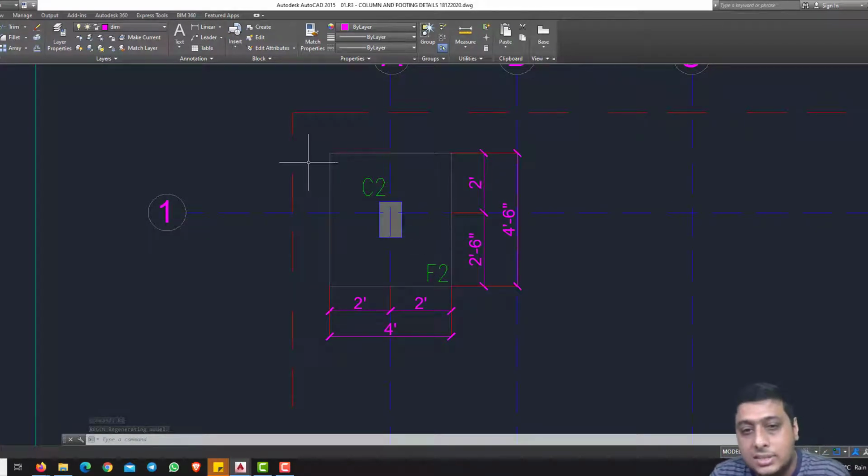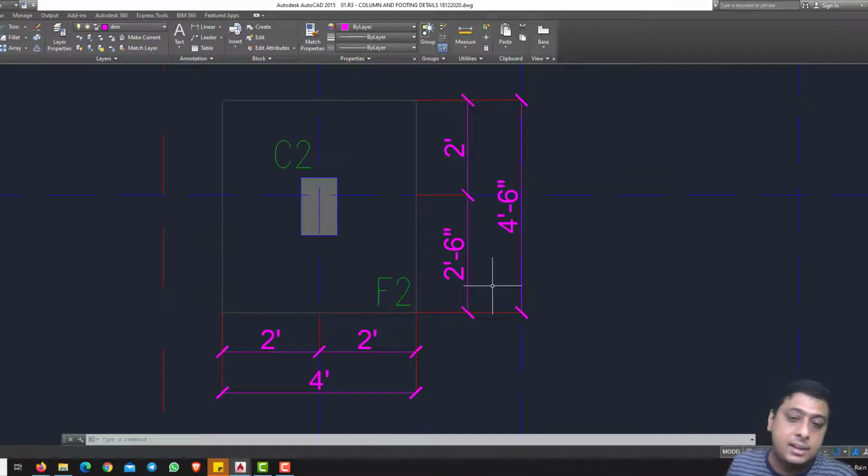So with respect to the foundation, the length and width of the foundations are very, very important. Generally, the length and the width of the foundations are given at a difference of 6 inches. Generally, it is a practice. Okay, rectangular foundation. Square foundation will have equal dimensions. For a circular column, we provide the square footing itself. Generally, circular foundations are not provided on the site.